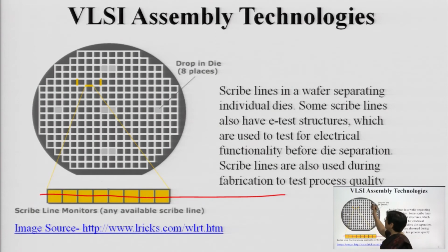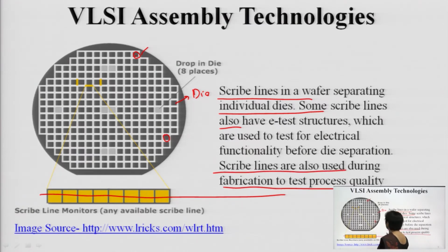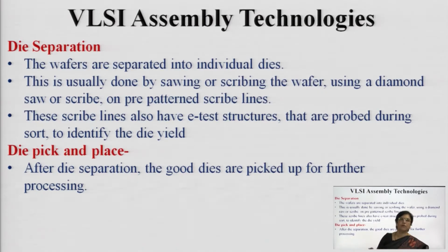So this is how your wafer thinning is being done, and then your wafer has those scribe lines. These are the scribe lines. Against these scribe lines, the wafer will be separated into chips. Each of these is one entire integrated circuit. So the scribe lines are basically separating them, and these we call dies. Now these are the dies which are separated thereafter. Based on these scribe lines you will be cutting them, separating those ICs. So this is basically the die separation.